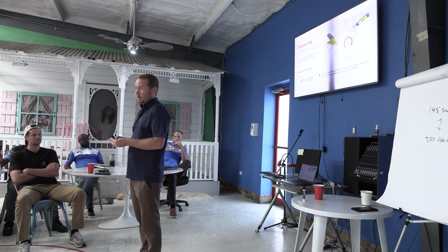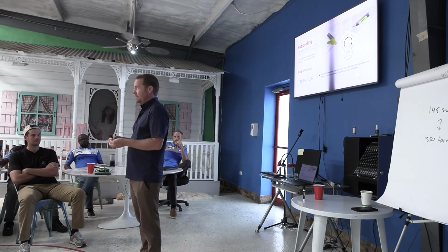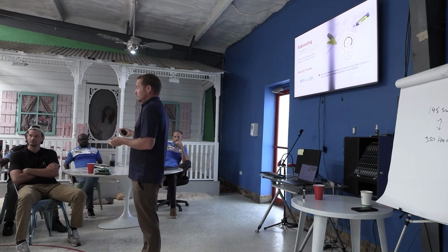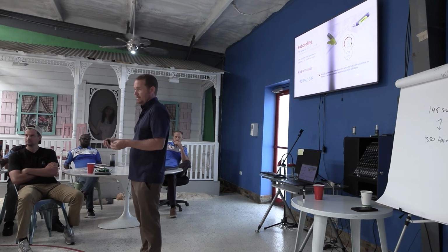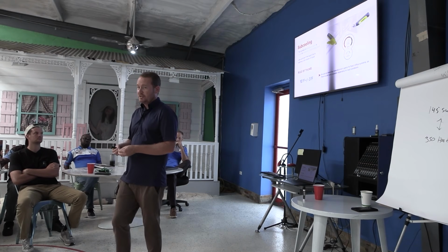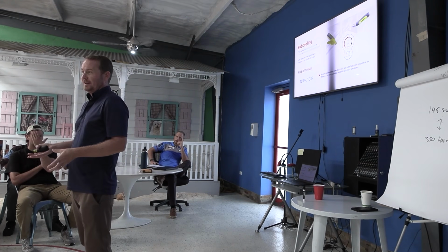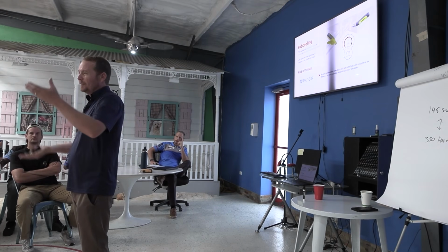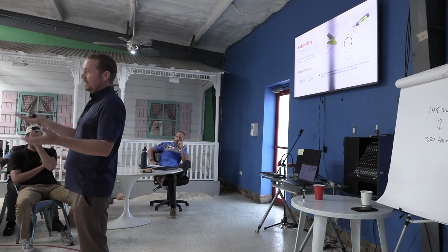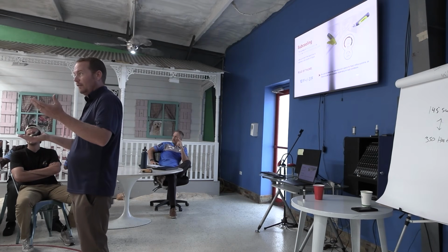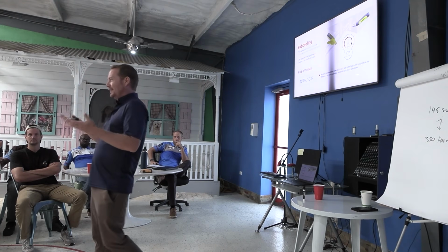So what is static pressure? It's right in the name. Is it a measurement of flow? Is it static flow? No, it's pressure. It's just pressure. It's telling you what the pressure is. And the pressure is dictated by the amount of air that's being moved in the first place, right? So it's kind of another one of these chicken and egg problems. It's like, well, my static pressure is good. Well, do you have good airflow? Well, I'm using static pressure to figure out if I have good airflow. Oh, right? It's a little bit of an issue.